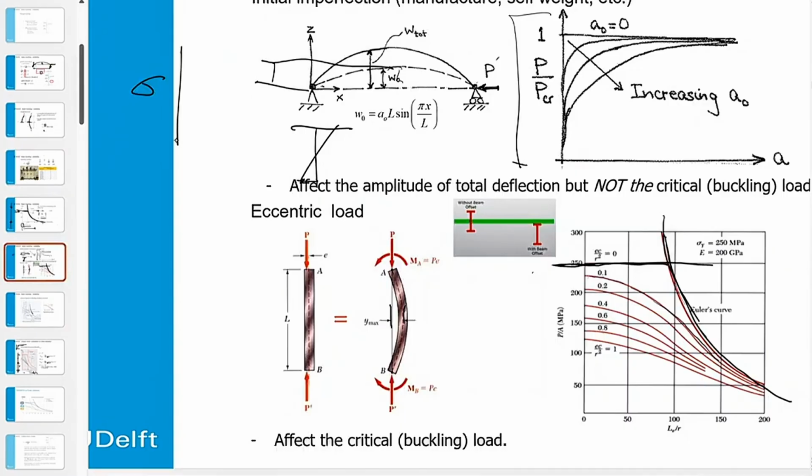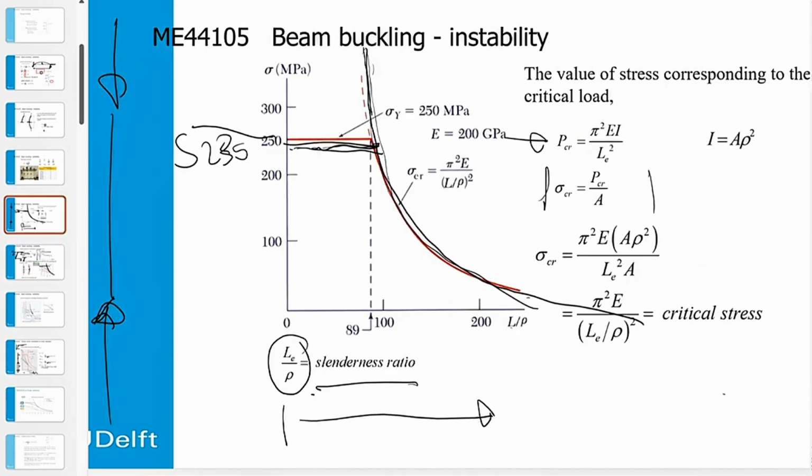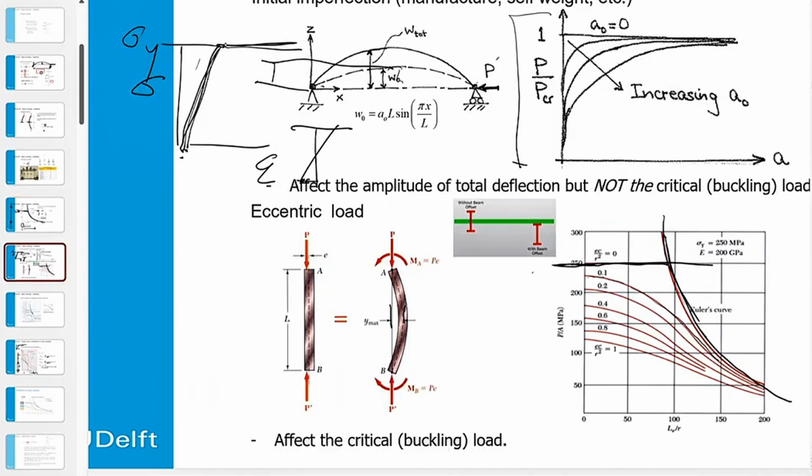If I have buckling stress, then this is my deflection. This is the curve which you take into account for this Euler-Johnson buckling. Up to the yield limit, it behaves linear, and then we have the yield limit, and that's it. In reality, we have an increase in stress up till the ultimate stress. So we have in reality some extra reserve capacity.